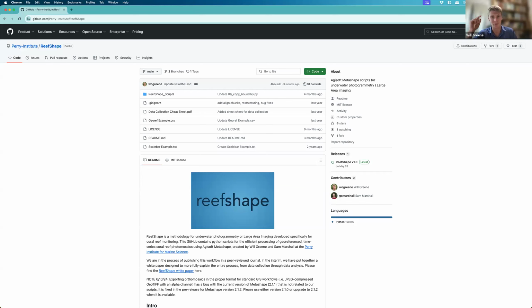So the first time that you run the script, it'll align all of your photos and then generate a three-dimensional mesh. And then you can manually go back in, define your scale and your georeferencing, and then run the script again, and it'll finish the process and execute the rest of it to generate your digital elevation model and the orthomosaic, and then export your data products. So it can be used if you're not using those automatically detectable markers, but it just can't be automated to the degree that it can when you do use those auto markers.